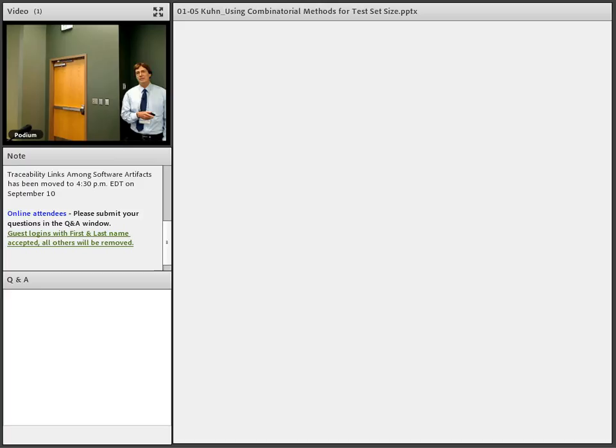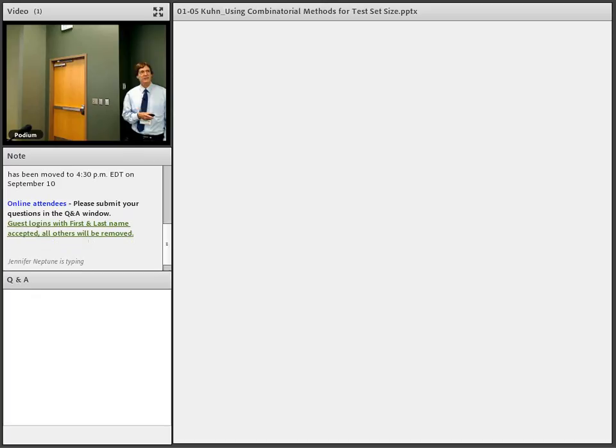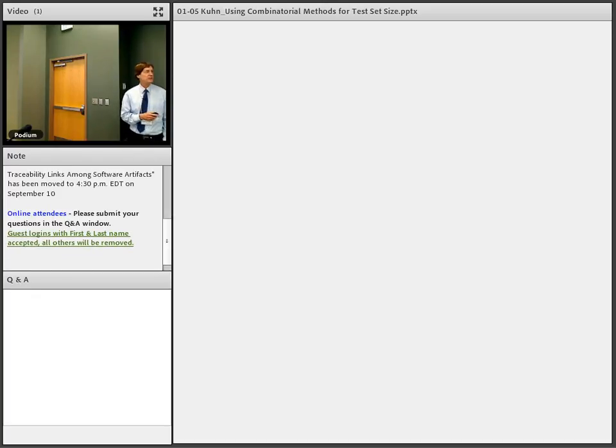And 10% of the naturally occurring faults are three-way, so we could expect to get 80% of those three-way faults. We are not guaranteed to get 80% because the 80% that we've covered may not be the ones where the faults occur, but on average, it's a reasonably good way to estimate it. If we add all that up, we get roughly 95% for this made-up example.